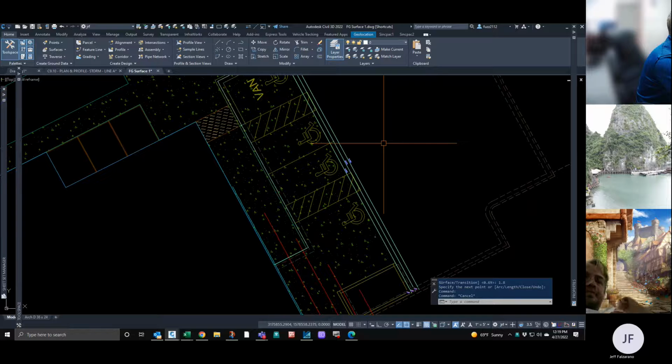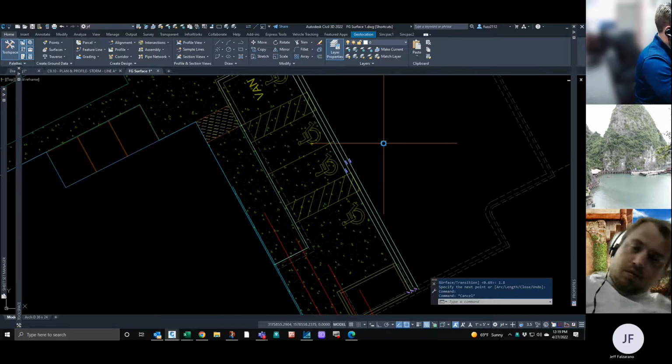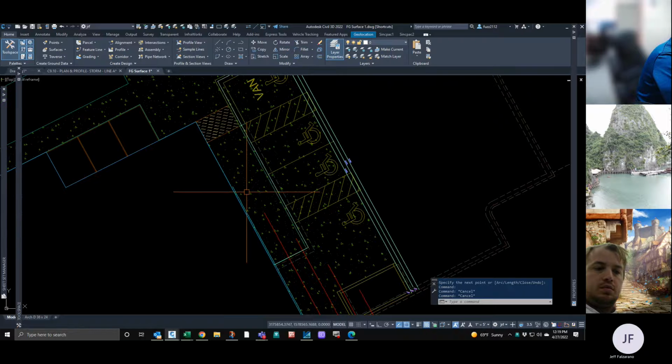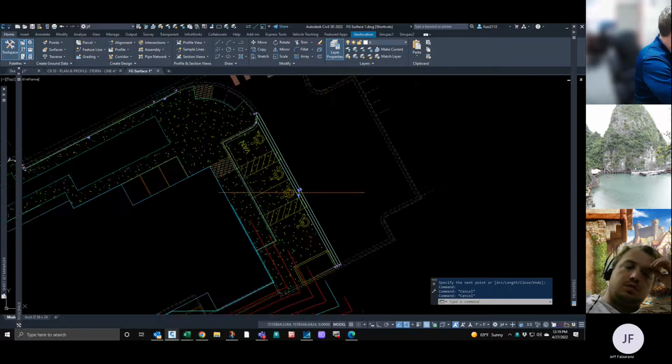Unless you're warping your sidewalk and it's going from sloping downward back to upward. Yeah, I'm going to have to change all these slopes. Yeah, but nothing over 2% and nothing under 1.8. That'll actually make things better. I'll just have to change it.